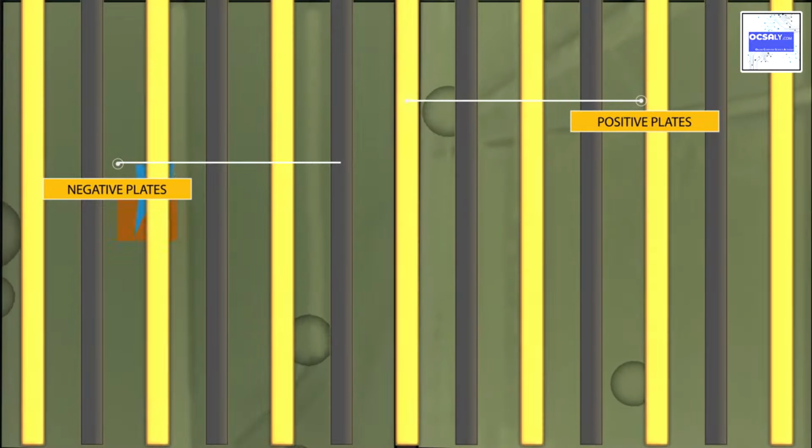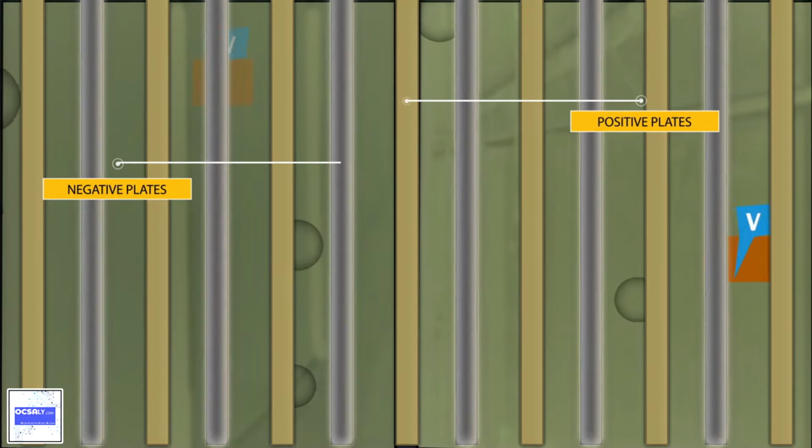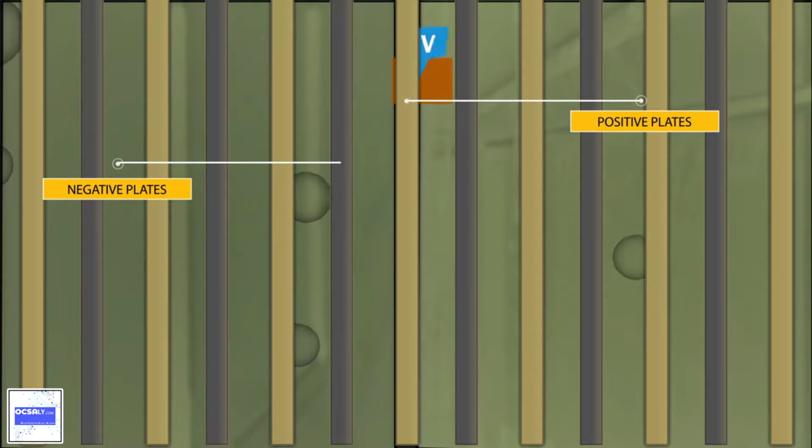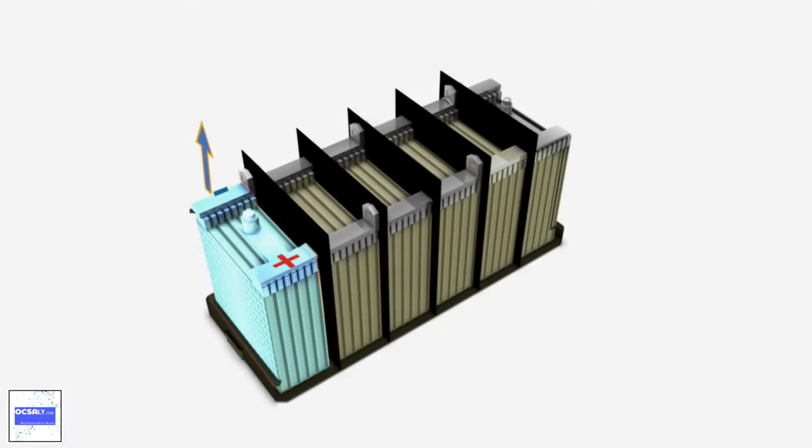Battery performance can be determined by its ampere-hour rating, but this is also affected by the ambient temperature. A cold battery will have a poor performance in comparison to a warm battery. A more useful measure of battery performance is its reserve capacity rating.